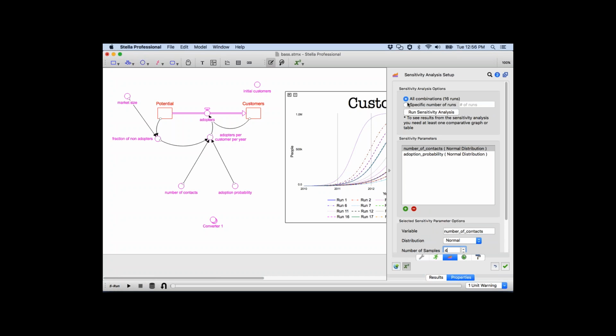But because we didn't have a sensitivity analysis set up before, this SRun button wasn't there. Therefore, I hit the checkbox so that the SRun button would show up. But you don't have to concern yourself with having to ever hit that green check mark. Just click out, click anywhere else, change the focus, and it will commit whatever your current change is to the model.